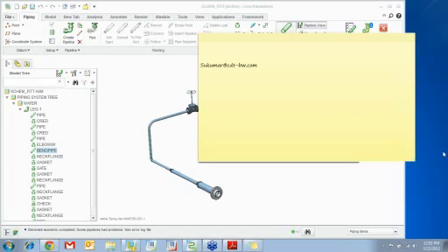the Router System Designer, and also the cabling and the electrical connectors, so that, say for example, if I have a connector that I'm going to use all the time, I can set up a symbol in RSD where its model name and its entry port parameters are already filled in. In that way, I don't have to do it manually every time the way I did it in the presentation.